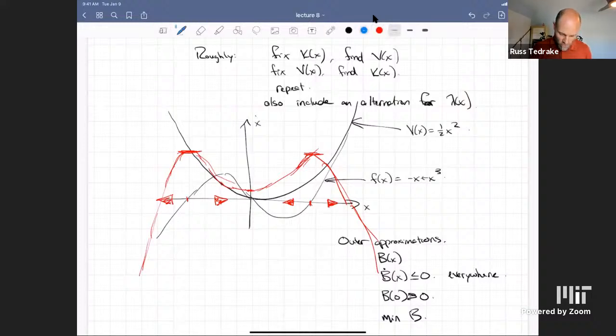I'll tell you how the control fits in a second, but first let me make sure that's true. So it's basically like the opposite of the Lyapunov function. Instead of finding a function that always decreases to the fixed point, it's finding a function that always diverges from the fixed point outside of a region. I don't want to call it the opposite. I was tempted to use those words too. Inside, it actually is acting like a Lyapunov function. Outside, it's still going downhill like a Lyapunov function.